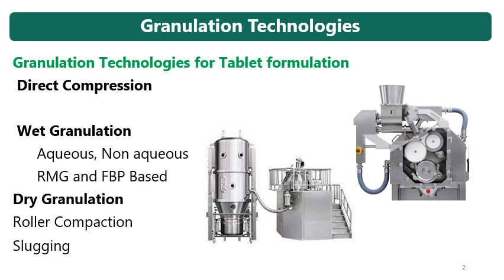Dry granulation involves the use of roller compaction to make the granules, and slugging is also a dry granulation process in which the slugs are prepared from the powder blend and then these slugs are broken down to get the granules. So slugging and deslugging was the earlier process for dry granulation. Nowadays slugging is not used for many of the molecules, and that is done by roller compaction. So whenever dry granulation is done, that time roller compactor is used.